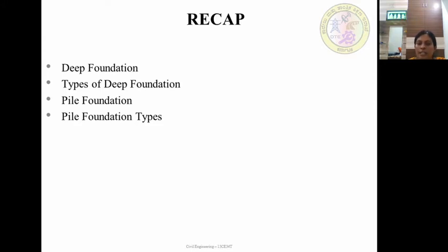These pile foundations resist the load acting on piles. We have to drive the pile till it reaches high density soils, that means it reaches hard strata. Next, pile foundations. Suppose the water table is very high. Due to the presence of this water table, soil could not withstand more load acting on it. So shallow foundation could not be provided in such situations. We have to prefer deep foundations.